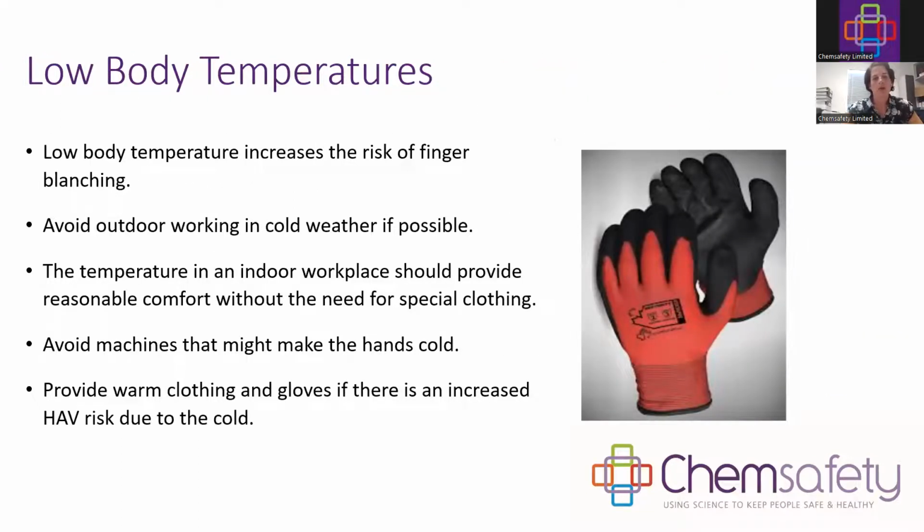Also, be wary of low body temperatures. Like discussed previously, the colder your hands are, the more likely it will lead to hand-arm vibration syndrome with the blanching of the fingertips. So low body temperature increases the risk of finger blanching. So you can avoid outdoor work. You can avoid working outdoors when it's cold weather.